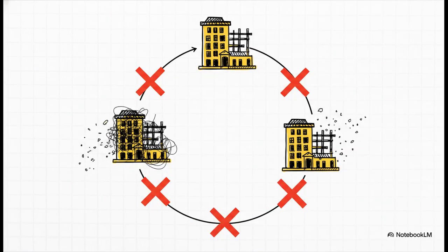So what does that actually mean for us on the ground? It means that while IFC is fantastic for sharing information one way or for archiving it, that perfect, seamless back-and-forth workflow between different programs, that's still a huge challenge. The translator just isn't perfect.